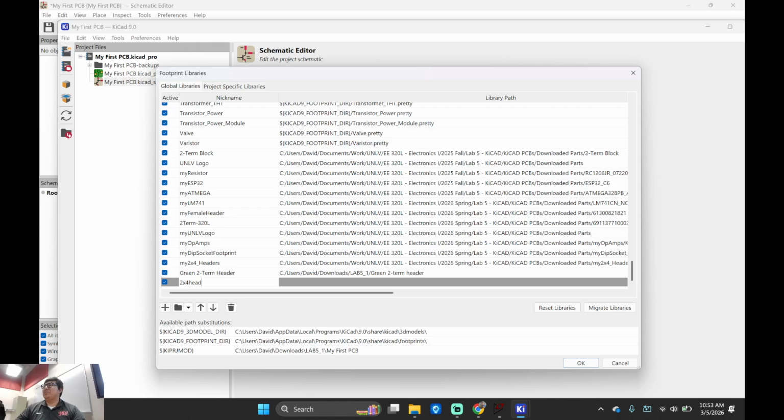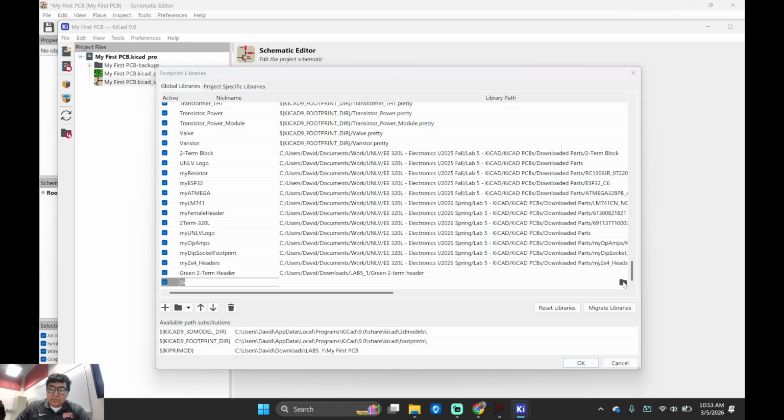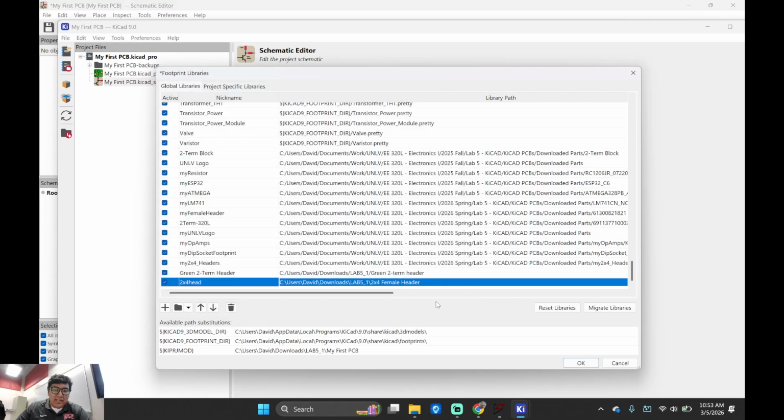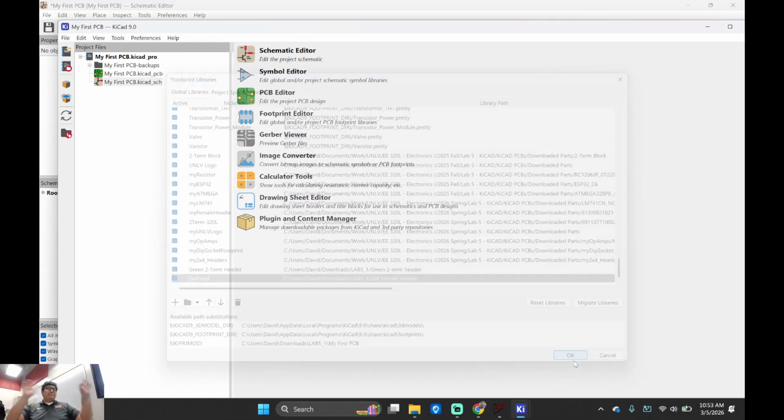Yeah, whatever. Just to keep it like, you guys seeing how I'm doing different names? Don't be afraid of using different names, whatever makes it easier for you, okay? Don't use the default, the weird one. Go ahead, even deeper in the levels. Call it whatever makes sense to you, okay? KiCAD is super open source. You can do a lot of cool things, okay? So, boom, boom, boom. 2x4 female header. Click there. And okay. Let it do its thing.